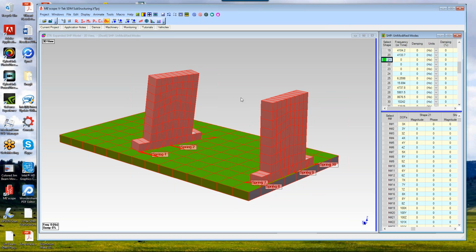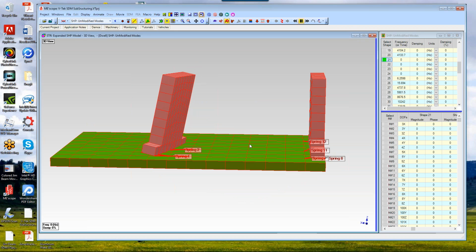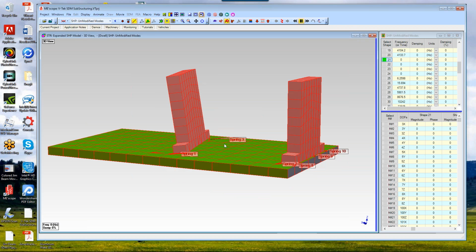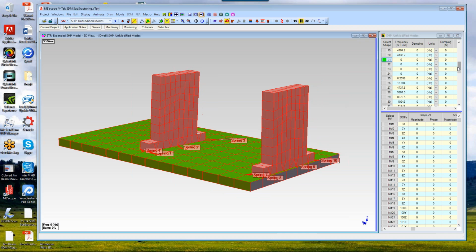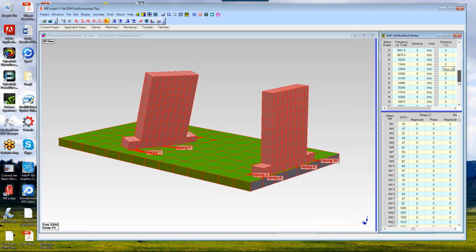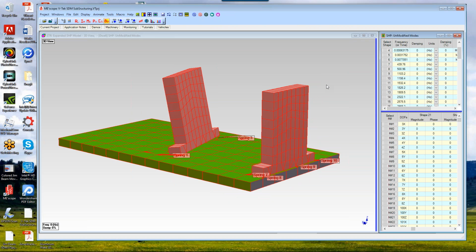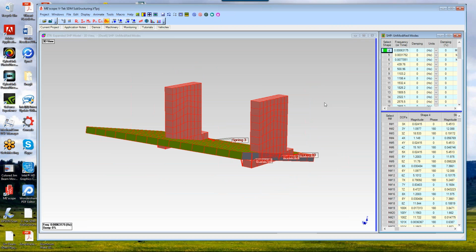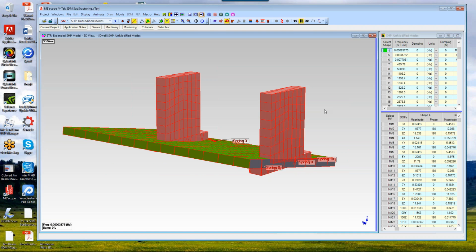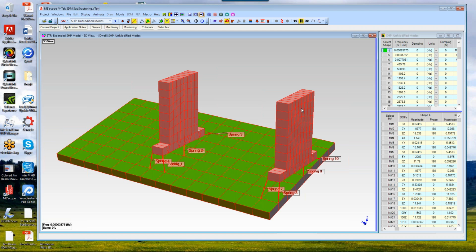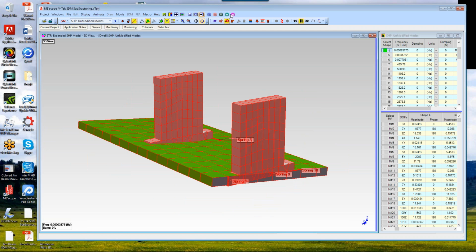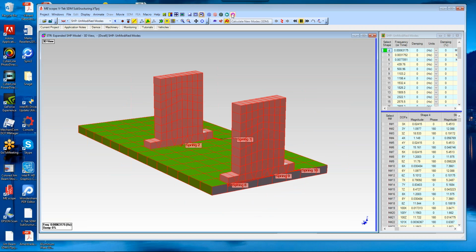see whether SDM now can see this bearing block here is completely free of the base plate, which it should be. All of its points are not connected to the base plate. And then base plate modes. See, we're not using the springs. Now the springs are going to connect between the top and the bottom. Let's go ahead and calculate new modes. And then we'll come back and look at some of this in detail.